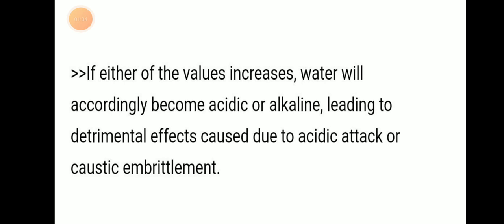If the value changes, the water will accordingly become acidic or alkaline, leading to detrimental effects caused by acidic attack or caustic embrittlement. So we need to understand that if the pH value is reduced, it will lead to acidic attack, and if it increases, it will lead to caustic embrittlement.